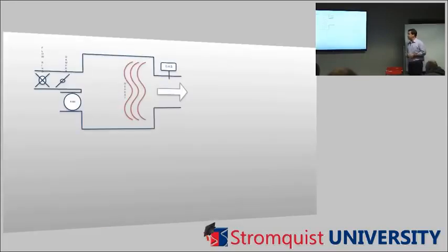All right, this is a typical VAV box. This is not drawn to scale. This is what you may or may not see up above your ceiling in a VAV box. For those of you who don't know it, we don't have any here, but you see them in large commercial buildings where you have the air handler units whose whole job is to push 55-degree air down the ductwork. And then the VAV boxes are over each zone, and they have a damper up here that opens and closes depending on what the space temp needs to be in that building or that zone, right?